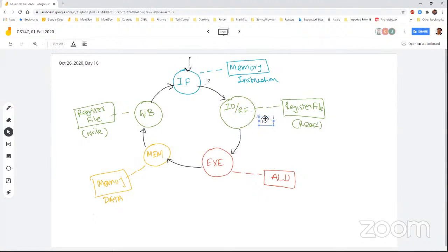And then when it goes into the exe phase, this one is pushed into the register fetch and I get another instruction from the memory, I3. Then I1 goes to the mem stage, I2 into the exe, I3 is pushed into the register fetch, and we can fetch one more instruction from the memory.